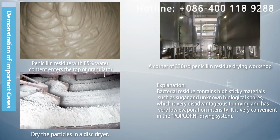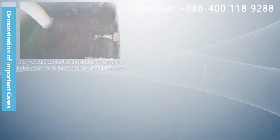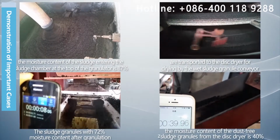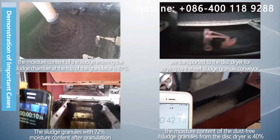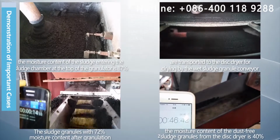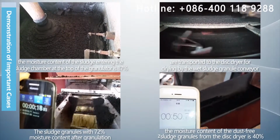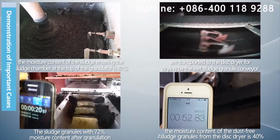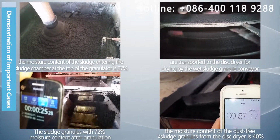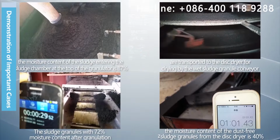The water content of the sludge is dried from 80% to 13%. The granulation dryer has a capacity of 100 tons per day. The drying efficiency cannot be matched by other traditional dryers. For this project, the sludge enters the silo at the granulator top with 87% initial water content. On leaving the granulator, the sludge becomes non-adhesive particles with good liquidity, high yield, and uniform water content.